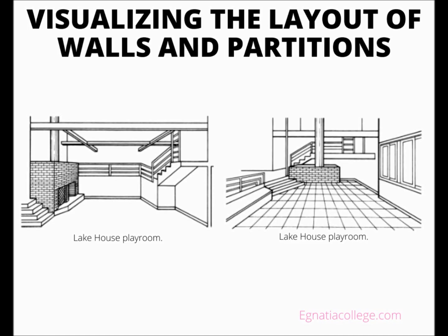A broken line in this area indicates the edge of a floor above. These floors can be seen more easily on the first floor plan. Also notice the location of the fireplace, which will extend up through the upper floor. The L-shaped stairs lead up to the first floor. It is obvious that this is not a full story higher, because a callout indicates that there are only 5 risers. This can be seen more clearly in the sections on sheet 4 of this house in your textbook packet.